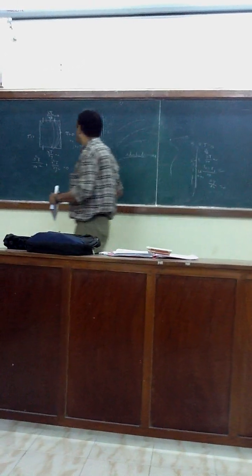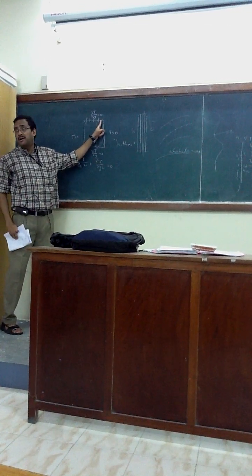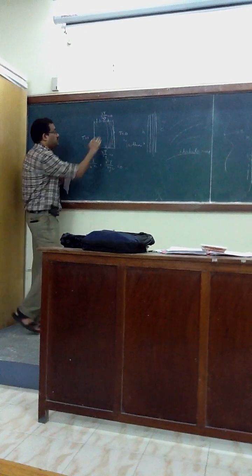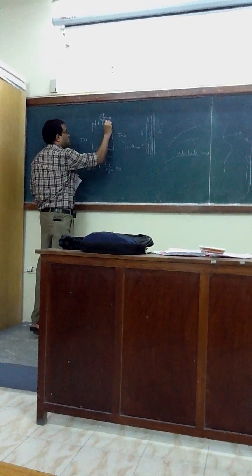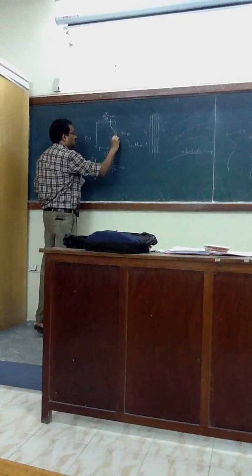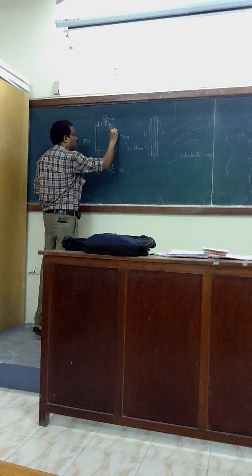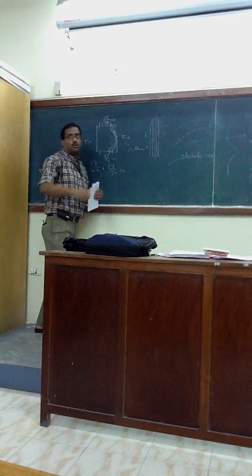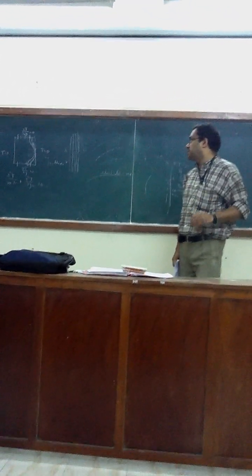Another possibility is, are they perpendicularly cutting here? No. That means that is not possible at all. So whatever the situation, the isotherms will be like this. If you say they will be like this, then some may be okay, but some will be passing like this, and this is not possible because 2 points won't have the same temperature. Then what's the next possibility?